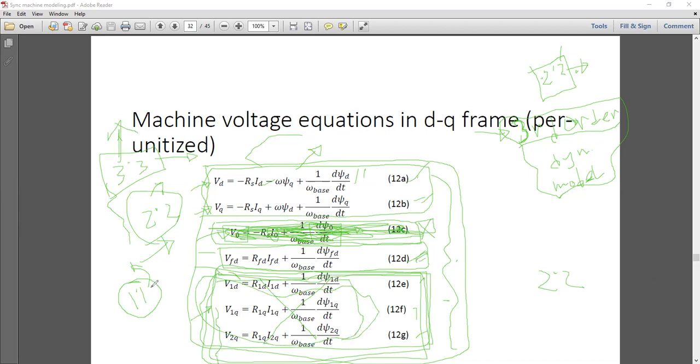First of all, you have to think of the physical presence of the coils of the model, and then you can easily write down the equations with the help of this derivation. That's why we took this 2.2 as the example. You can increase or decrease the dynamics of the model pretty easily from this. Our target for this course is to reduce the model size, so we get rid of all the damper coil dynamics and equations.